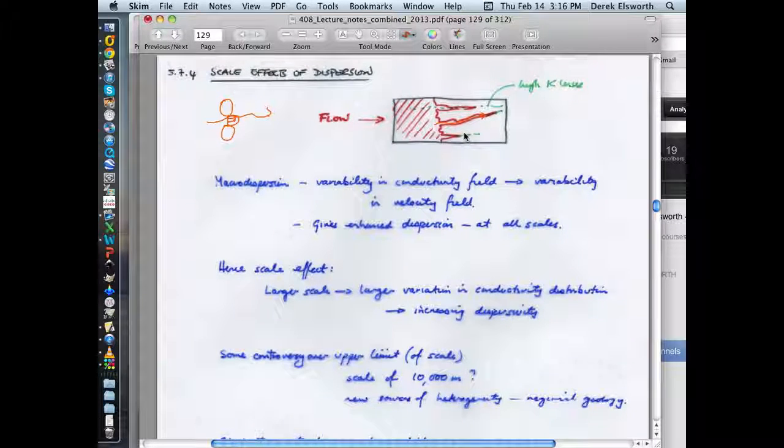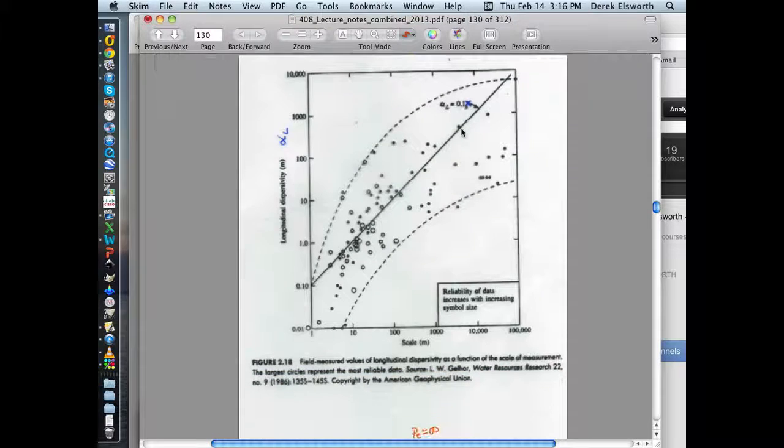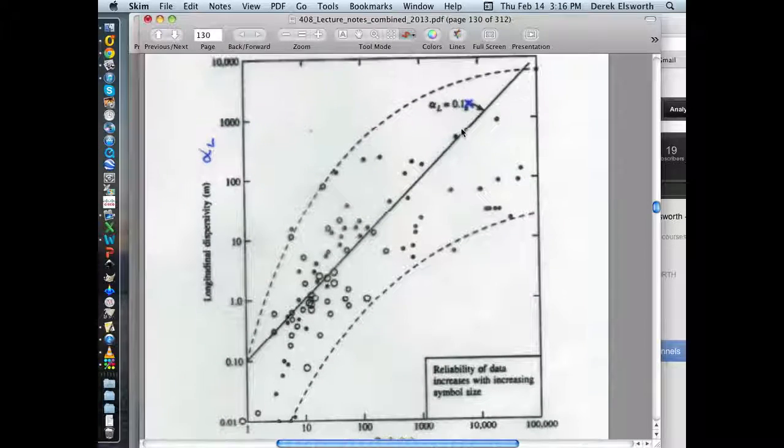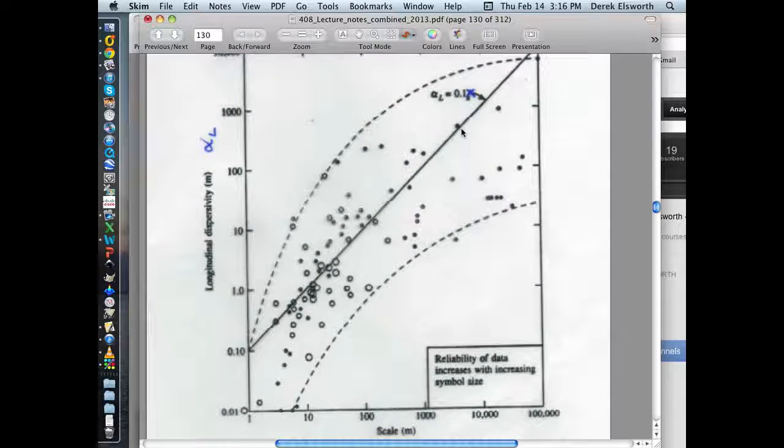And so the mechanics of dispersion is responding really to the fact that you have this heterogeneity within a system which allows some areas to travel faster than others, and as a result you get some spreading occurring. And so you get some very interesting behaviors if you look at, for instance, a whole bunch of observations from natural gradient observations. And so this is exactly what we've talked about doing today. We've just gone through the case of trying to figure out exactly what dispersion coefficient should be for this Borden site. And we calculated the value of this longitudinal dispersion out of it.